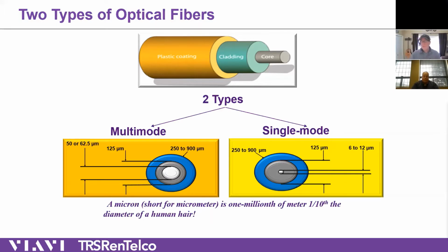So we look at single mode fiber. That core, the center white area of our picture, is roughly 9 microns, right? To put that in perspective, a 9 micron core is about a tenth of the size of a human hair. And that would be on someone like me, whose head is covered by the hat, I have pretty thin hair. So it's a really small core, which is expensive to build and expensive to make. And now your SFPs or your lasers have to actually be lasers and not just LED diodes, right?